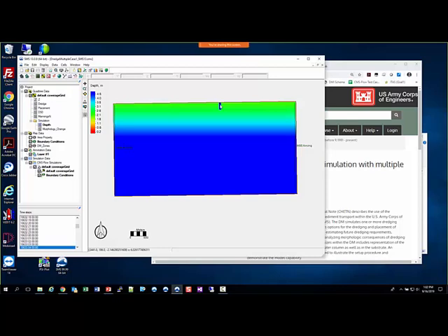And so it took a lot of time getting each one of those alternatives set up. Well, we've developed a tool with SMS 13.1 that will help automate that, so you can plan these things in advance, and it actually creates more exact volumes of material, and it also tapers the edges and makes sure that you're not violating slopes too much, and then you're ready to go.